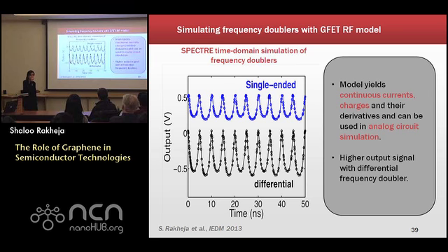Did you consider the mismatch between those? Yeah. So mismatch will actually make this go very bad. It's much worse for single-ended topology because it doesn't have a matching transistor with it. Even for the differential also? Yeah, it will make it much worse. All right. Good.